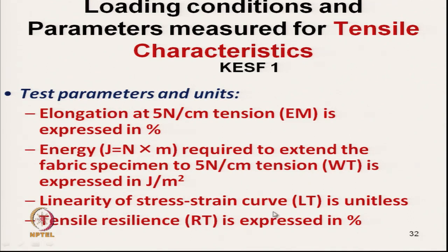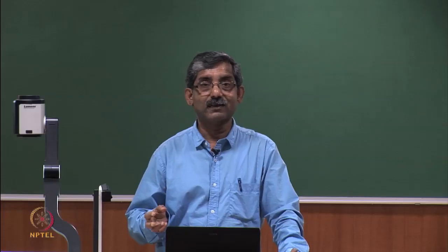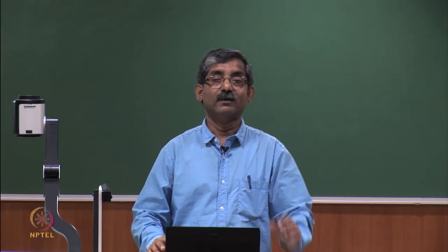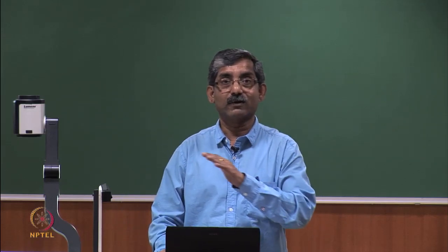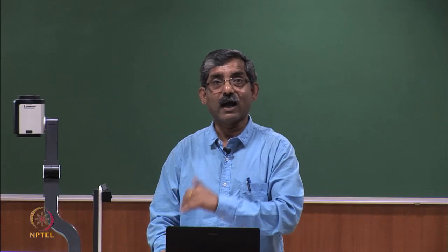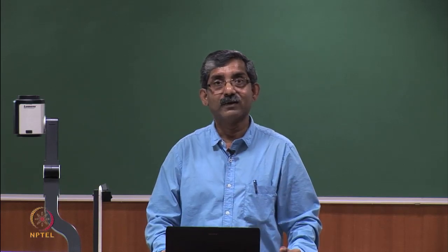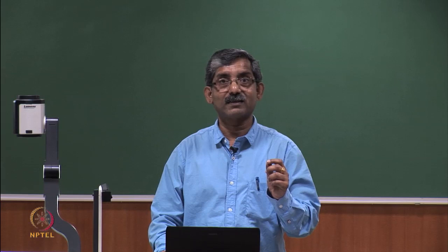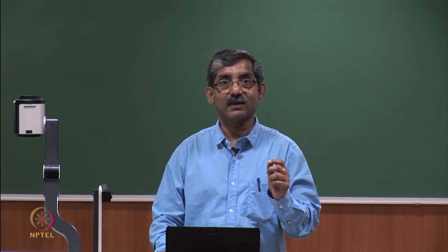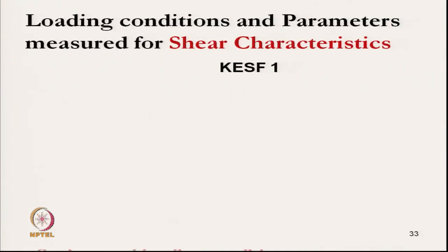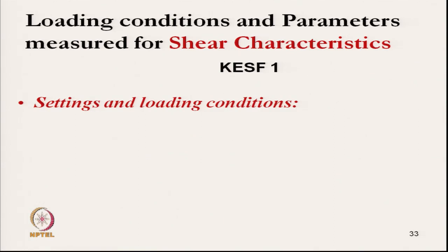Linearity of the stress strain curve, LT, is unitless, as I have already explained. Tensile resilience, RT, is expressed in percentage, which is the ratio of the energy of the recovery curve to the loading curve. These are the tensile related characteristics.